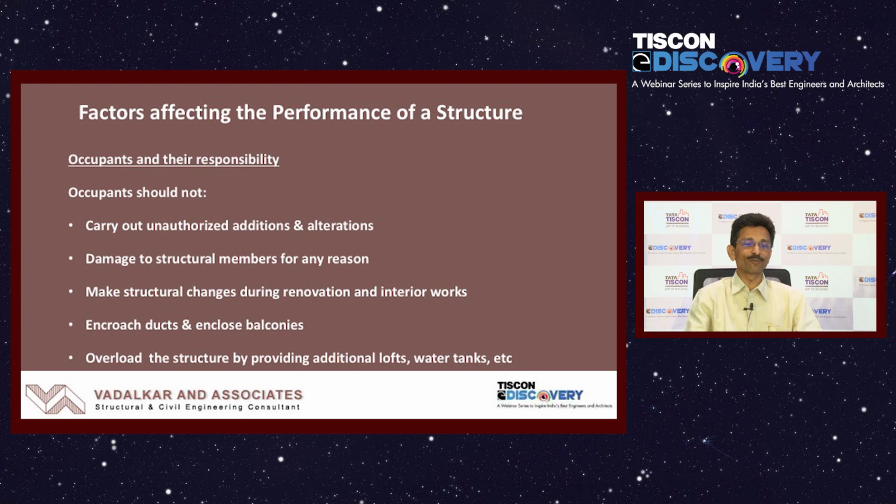And finally, I am coming to the occupants. What is the responsibility of the occupants? That is also very important. They should not carry out any unauthorized addition or alteration. It is generally observed that after the building is occupied, every flat owner feels that I am the owner of my flat, so I can do whatever I want. But that is not true, because it is part of the entire structural system.